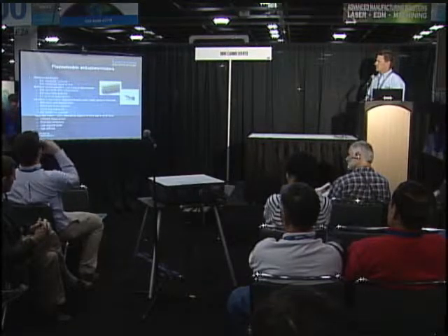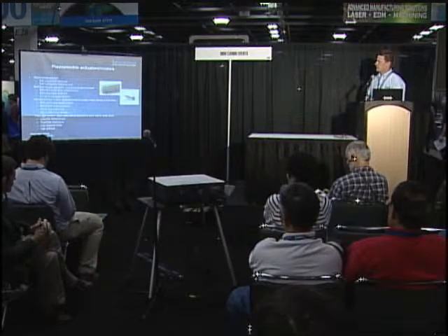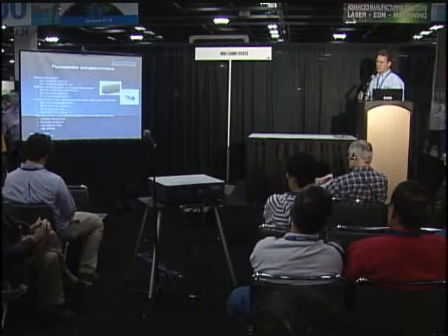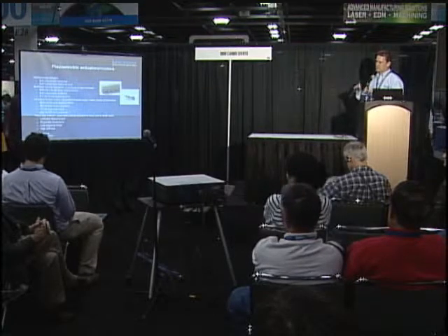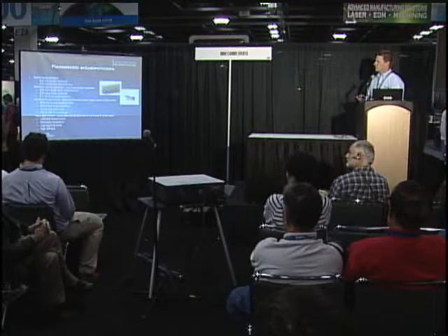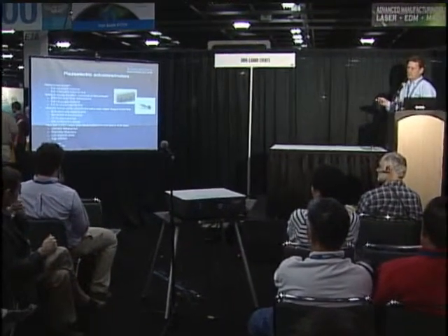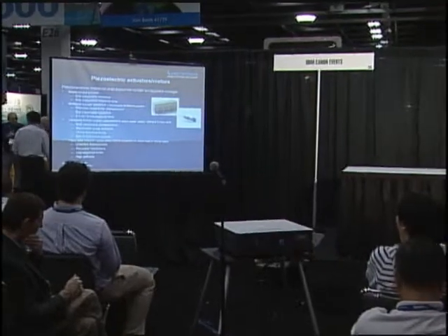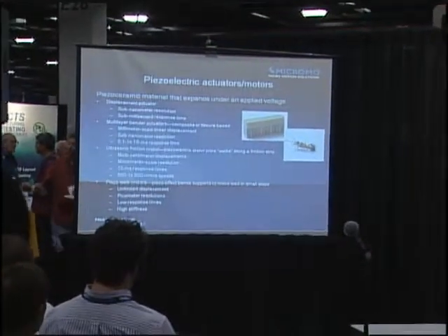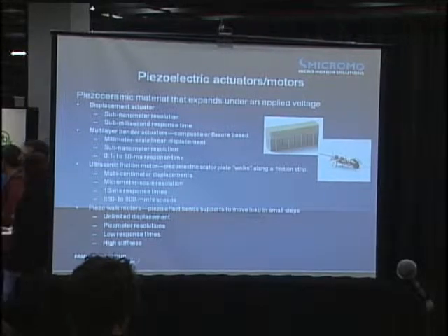As I said before, you're looking at nanometer resolution, and in these motors, as you see here, they have a walking function. So they have a ceramic substrate that they're actually moving with the piezo elements, and they tend to behave sort of like a stepper motor, where when you shut the power off, they'll stay in place. They're not going to drift. And it's basically a voltage-based movement. The drivers or drive system for these types of motors is not very complicated at all. It's a nice package.